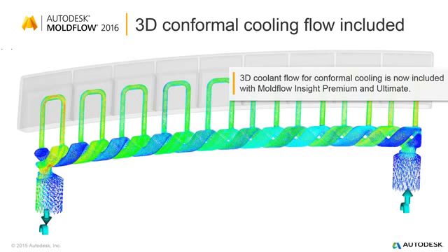Another thing we did in this year's release is add full conformal cooling, now completely within Moldflow. Whereas in the releases up until now, the 3D flow inside the cooling channels could be done, it required an Autodesk CFD license for both the solver as well as the design study environment, the user interface.